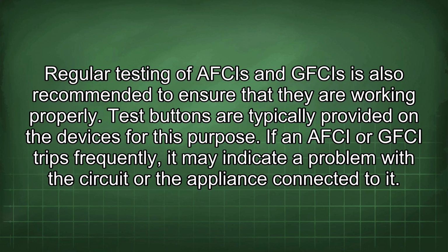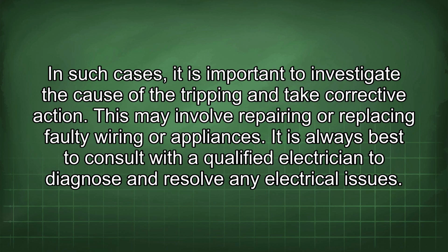If an AFCI or GFCI trips frequently, it may indicate a problem with the circuit or the appliance connected to it. In such cases, it is important to investigate the cause of the tripping and take corrective action. This may involve repairing or replacing faulty wiring or appliances. It is always best to consult with a qualified electrician to diagnose and resolve any electrical issues.